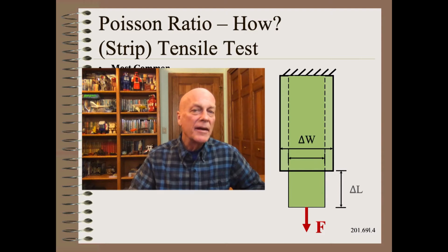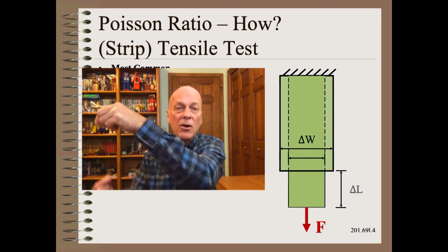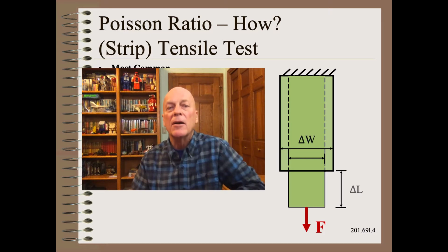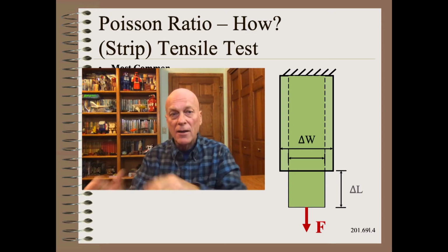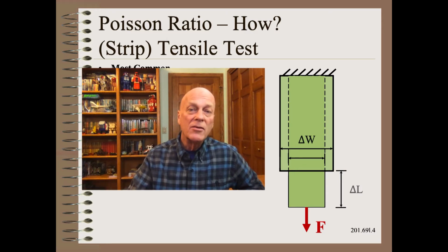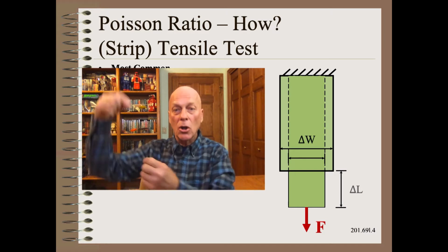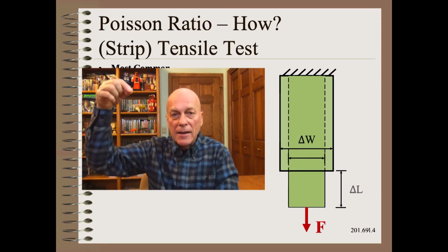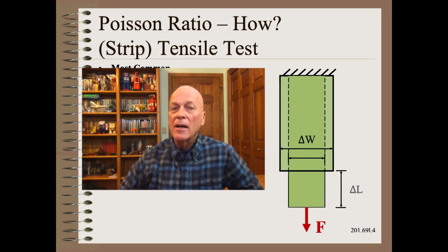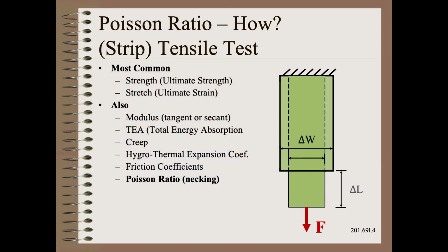It is done with something like a tensile test. We pull a web with a good fraction of yield simply to get better measurements, then somehow measure the changes in length and width. For low modulus nonwovens whose properties are not on the internet, I try to hang a very long specimen against a wall and deadweight it. Length and width before and after applying the load is recorded. Of course, that simple method would not work for stiff materials because the strains would be too tiny to measure with a ruler or tape measure.